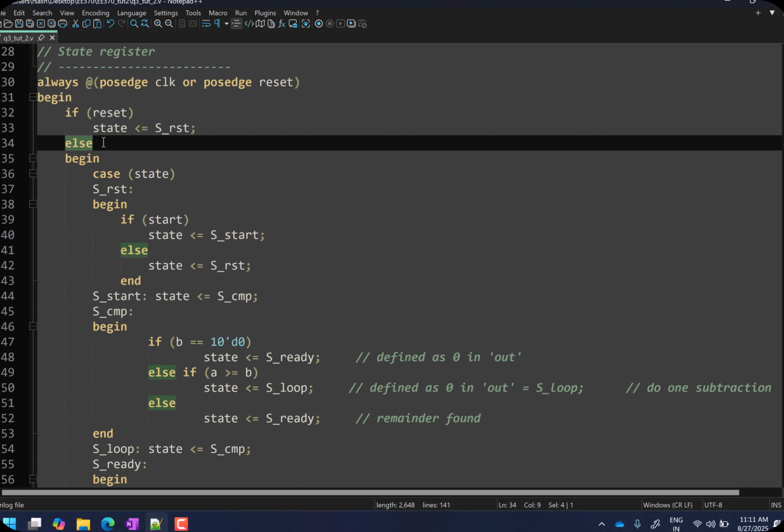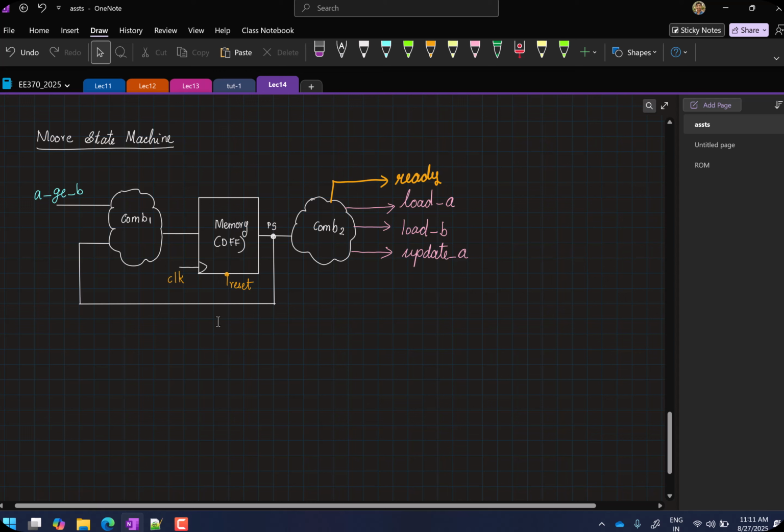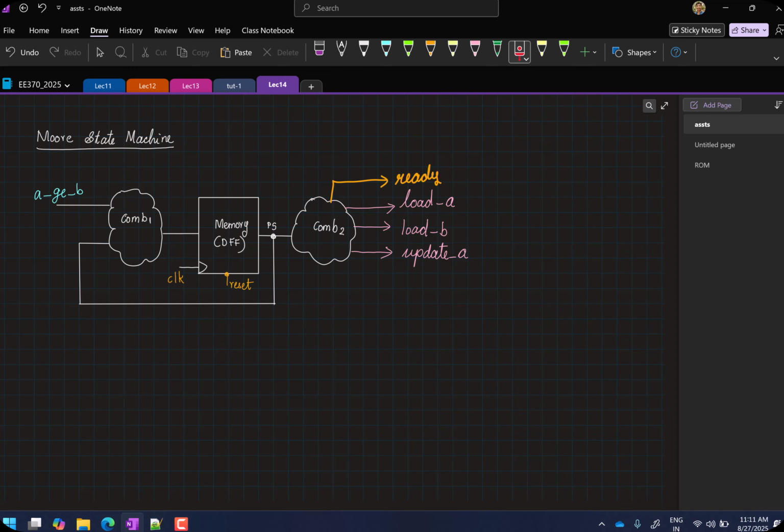This is what should happen in the clock condition. If you are in reset, you are looking at this pin, your output goes to 0, or a particular value of state that you want it to take. Else you are looking at the clock condition, then the effect of this combinational circuit should appear here.